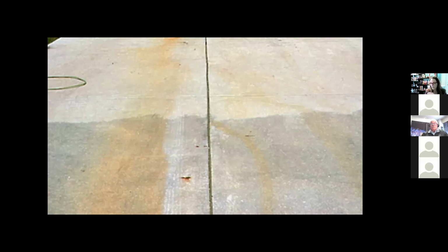This is not temporary. Don't look at the streaks of the car tracks, but look at the fact that the bottom half is darker than the top half. This is going to last in a structure, and it may or may not be acceptable. What probably happened here is that they waited to place the second batch, and they wanted to do the final finishing operations at the same time. So they added some higher amount of calcium chloride to the second batch. Calcium chloride is allowed on non-reinforced plain concrete. However, just know that if you only add it to one half of your mixture or your design, I mean, because it's two different trucks, then it's going to change the color. So that's an issue.